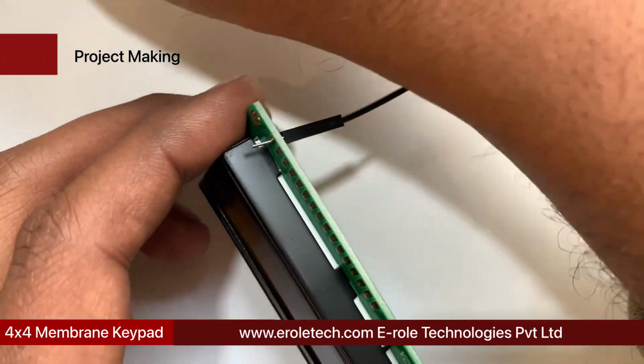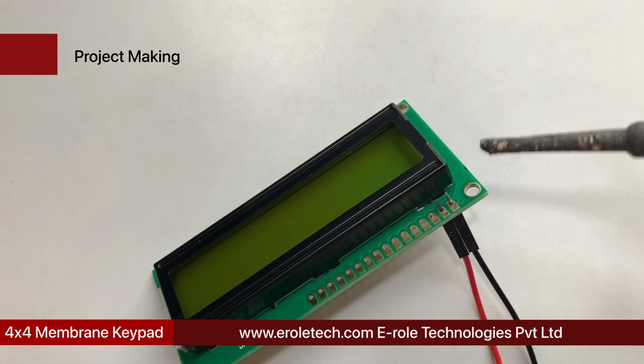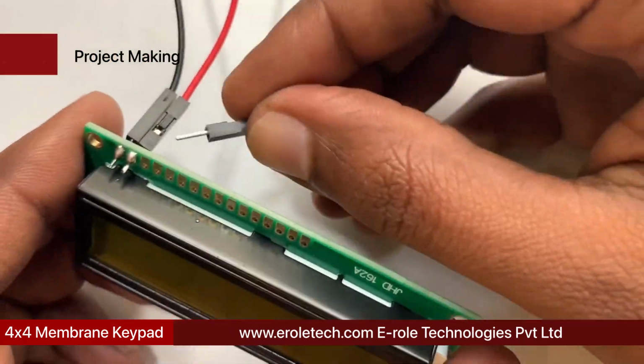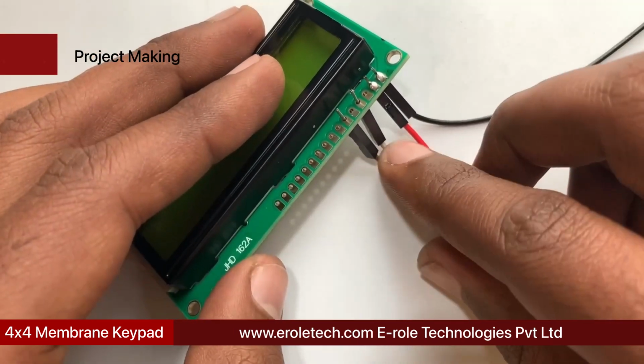Now we will solder a black wire at hole number 1 and a red wire at hole number 2 of the LCD display. Now we will solder a white wire at hole number 4 and a brown wire at hole number 6 of the LCD display.